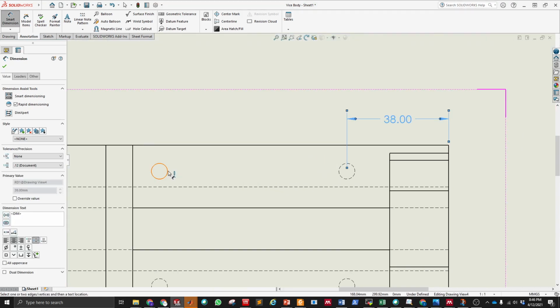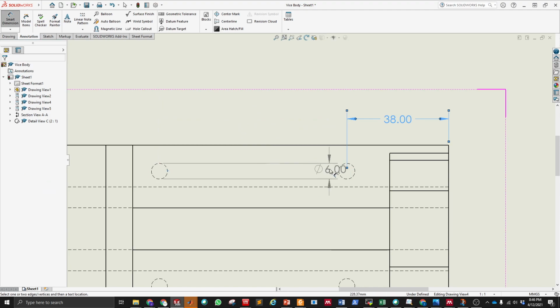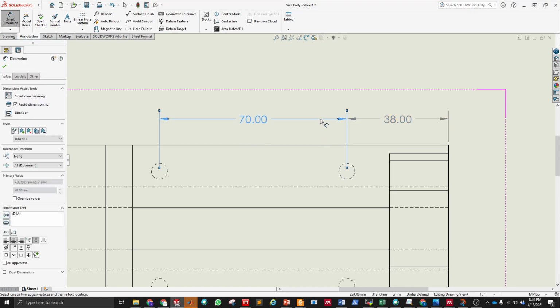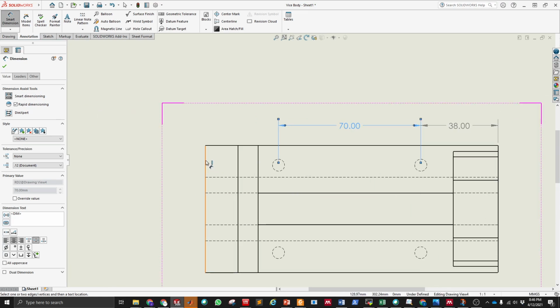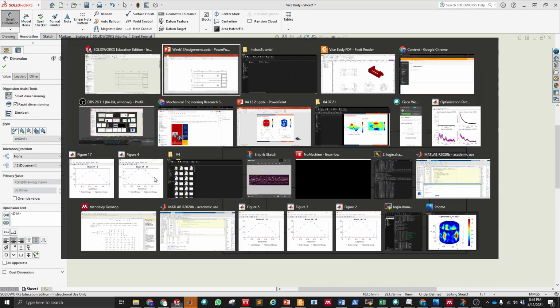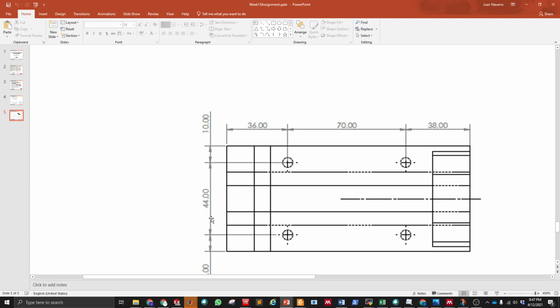Also, you can select to place the dimension as you prefer, also higher or down. But doing it with this control, it has by default this distance, which is like a standard distance. So it's better if you just use either the half or quarter circle that Solidworks gives you the option to. Okay, now we have these other 3 dimensions here.